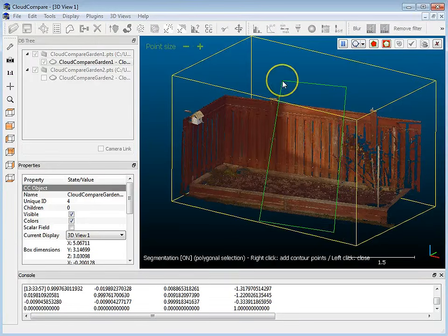What I would recommend, and I'm not going to show it to you here, is if you have two dissimilar point clouds, but parts of them are the same, cut out the section that is dissimilar and leave just the parts that are the same, register them, and then apply the same transformation to the part that you had cut out. I know it may sound a little bit confusing.